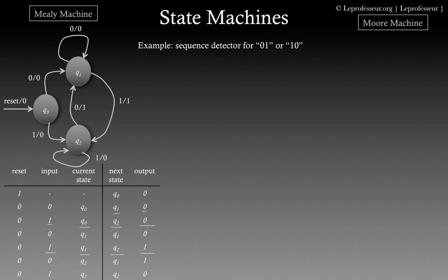So you have input reset, and you are by default in the Q0 state, and because you have not detected the sequence yet, notice that in the state diagram circle we are representing the state as well as the output of that state, while in the Mealy machine we were representing the output on the arc along with the input. A minor difference in the state machine diagram.